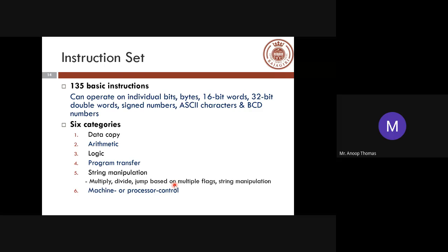You will have complexities increasing. The buses will change, the address buses will change, and the number of instructions used will change. You will have more blocks inside your architecture, more pipelining setups. The pipeline might get increased. These are the things which happen as you move from the basics of the 8086 to the 286, 386, 486, and Pentium processor. So that's the basic idea.